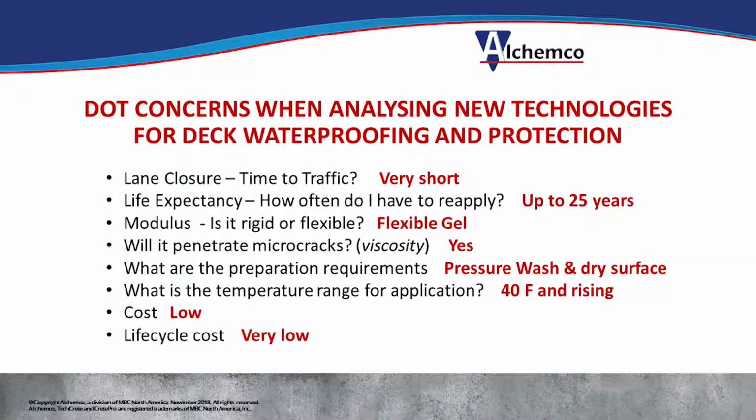For preparation, the area should be clean and dry, so usually just a pressure wash is enough. One of the limitations of this material is that the concrete should be completely dry. That means no standing water. If we had rain, visually, the area should be dry. We don't have to measure the moisture content of the structure, but visually, the area should be dry. So usually we ask for about 24 hours with no rain.